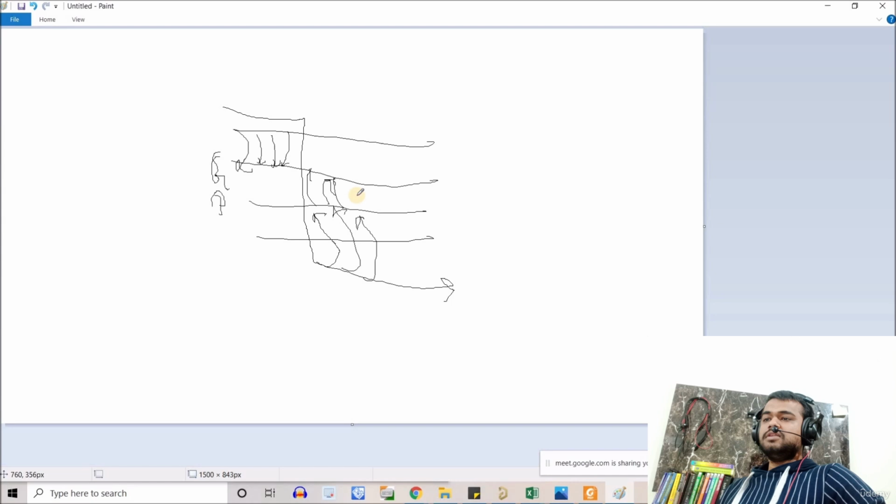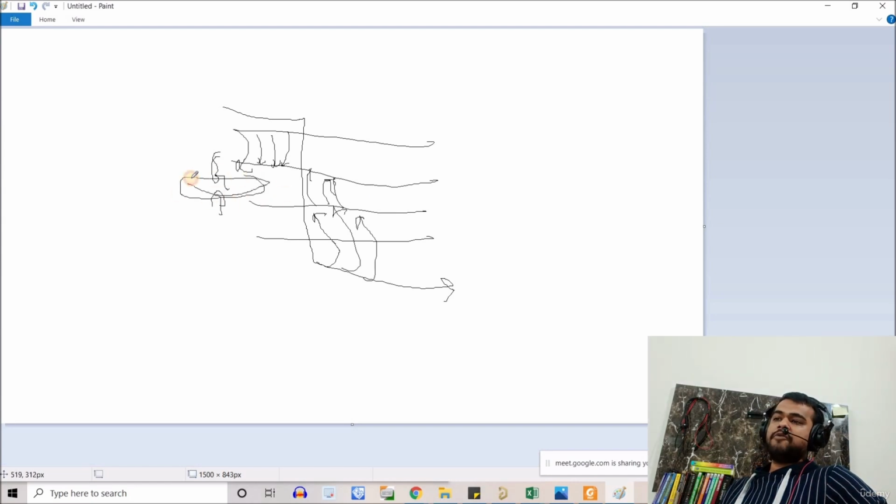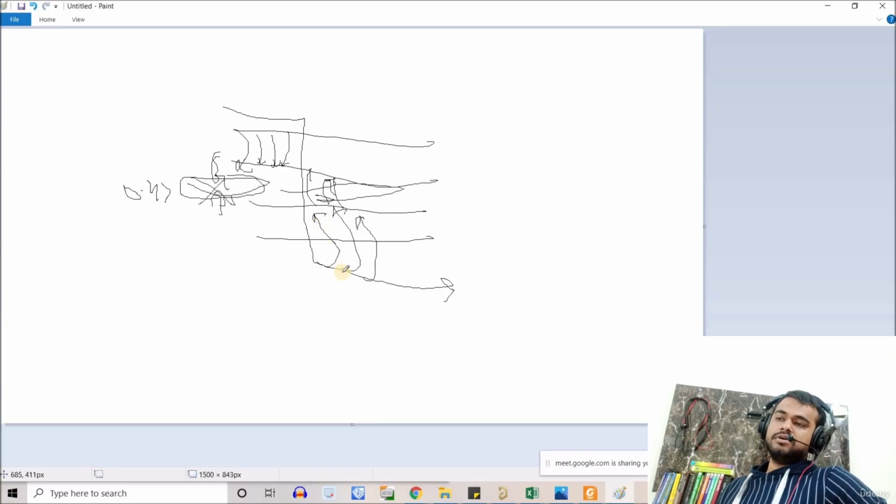Now let's suppose the coupling between ground and power is really bad. For example, we have a very huge gap between the ground and power, greater than 4 inch. So this coupling will be weak, right? And the return current will not get a low impedance path here.